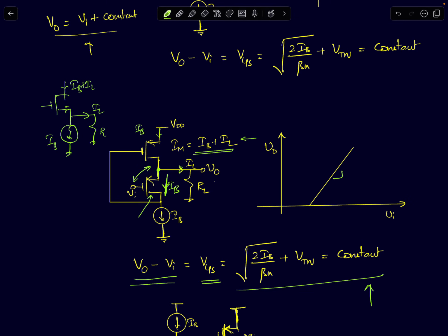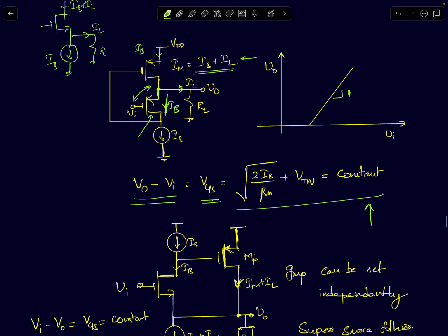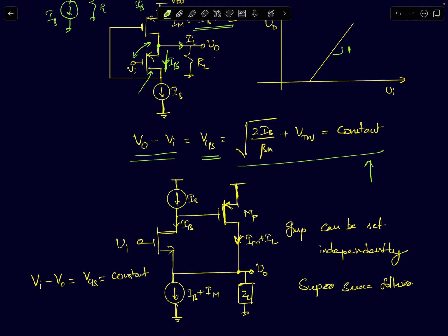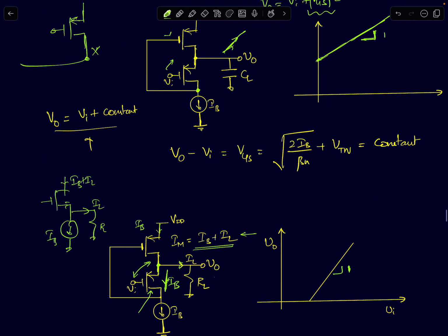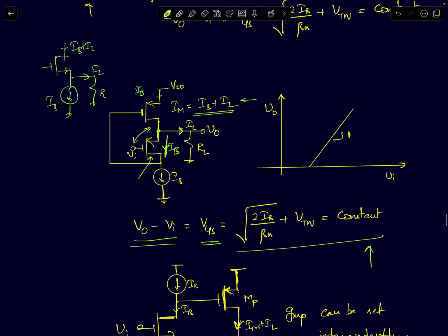Now you see, I've gotten a very linear characteristic without spending infinite current. Okay, without spending infinite current, I got it. I've just shown you an example of a PMOS based flipped voltage follower amplifier with some modifications to it, and I was able to achieve a near linear characteristic for a resistive load as well. Okay, because that load current is entirely flowing through a PMOS.